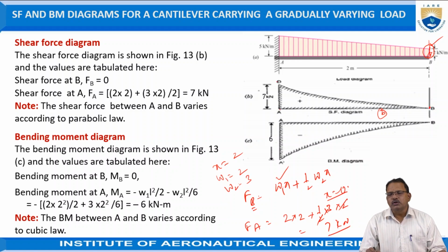At the other end it is equal to 0. Because of this force, it is acting in the downward direction with respect to point A, that is the fixed end. So this shear force is treated as positive. Hence, in order to draw the shear force diagram, from B draw a line vertically downward. Again from A, one more vertical downward line. These parallel lines represent the length of the beam. At a convenient distance, draw horizontal lines to represent the length of the beam.